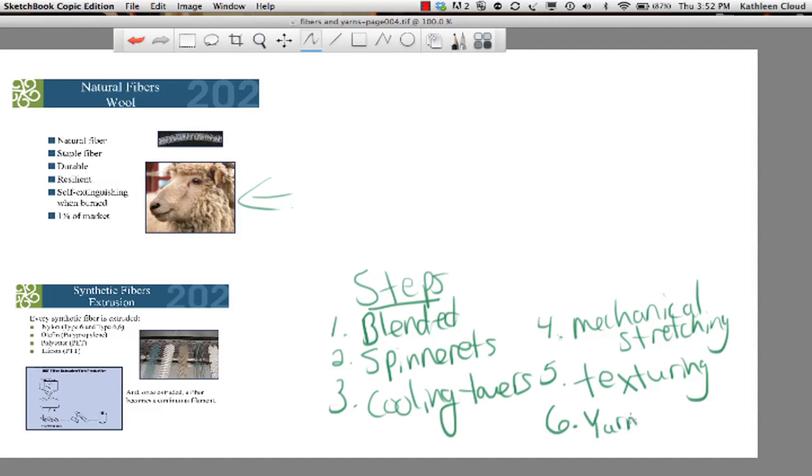Yarn take-up. From this point, yarns can be twisted together or air entangled with threads. However, it is important to understand that step 6, the take-up, is not the final step. All yarn will have a twisting and heat set step. This is the same as spun yarns.